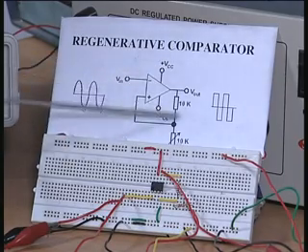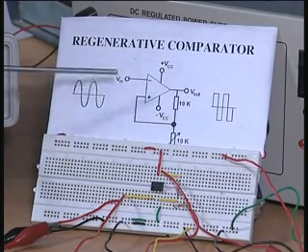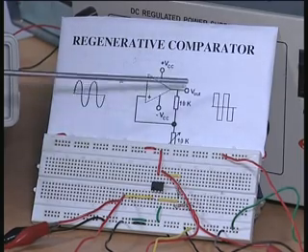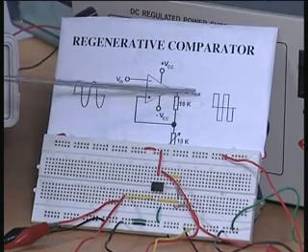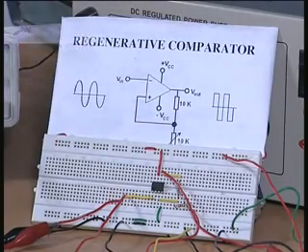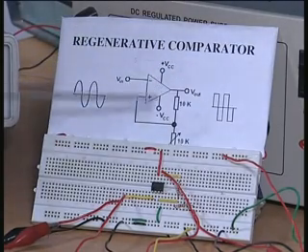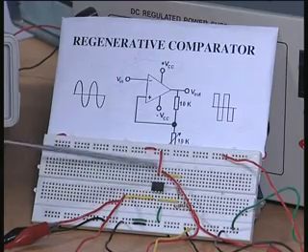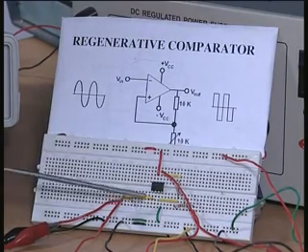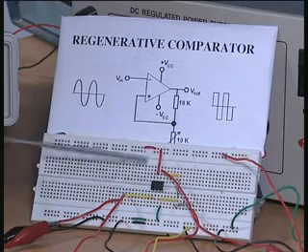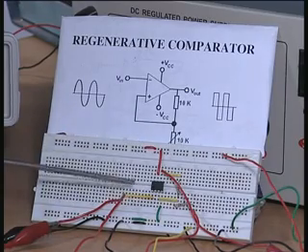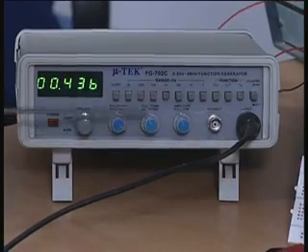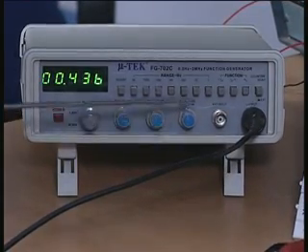In order to show the hysteresis, what we have done is, I have taken this input and given it to the x axis, and the output I have given to the y axis, and I am trying to look at what happens in the oscilloscope. Now I want you to look at the circuit. Again this is a 741, you can see the plus Vcc and minus Vcc are connected to pin number 7 and 4, and the input is connected to a function generator which we also saw previously.